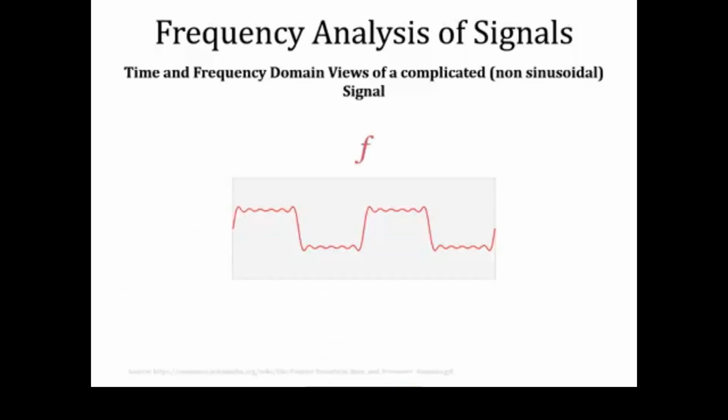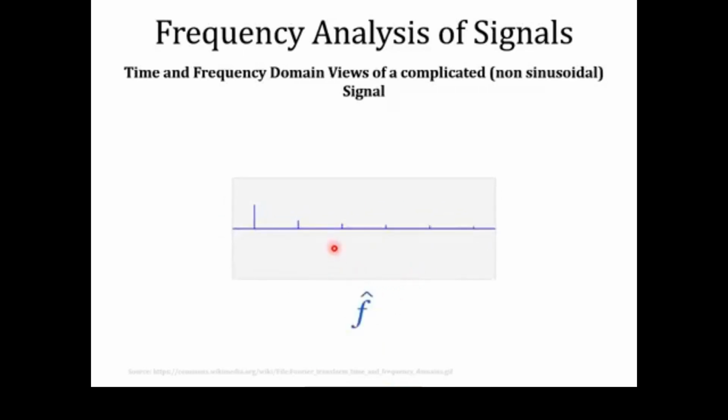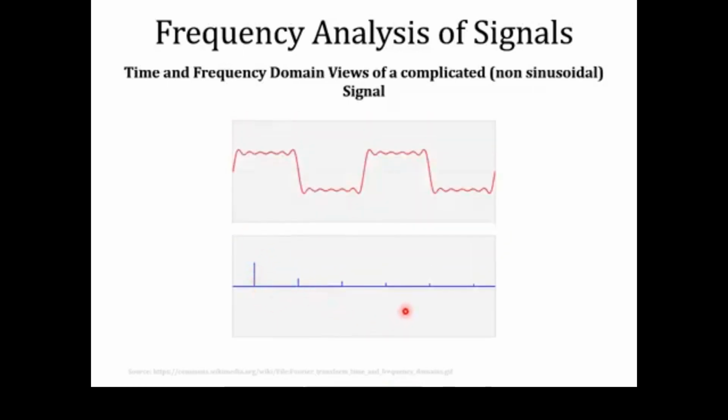Now let's conclude the lecture on this animation. Suppose the complicated looking signal is this one, which is represented by red color, and it's simply a composition of various cosine and sine waves. And if we will look at the ingredients of this signal in frequency domain, every sinusoidal component will appear as a spike. So the description of a signal in frequency domain is so-called signals spectrum, where the height of each spike will represent the strength of each sinusoidal component present in a given signal.